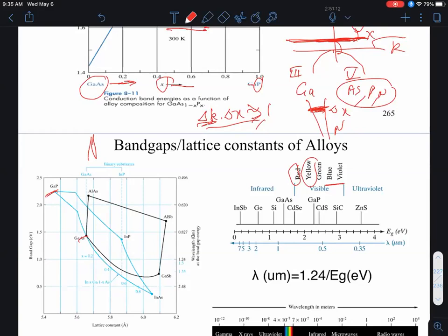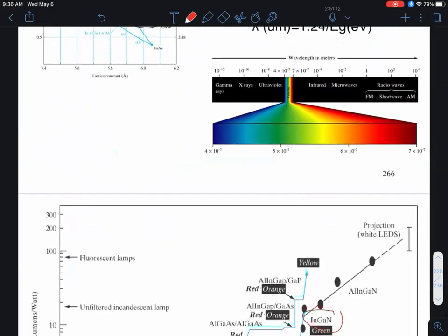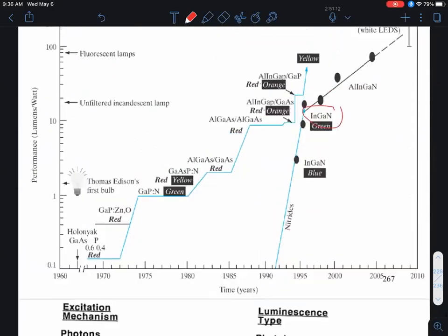Not only that, for some very interesting reasons, even though these nitride semiconductors are actually not very defect free, they have a lot of dislocation type defects in them, for some reason Mother Nature was kind to us. She decided that these defects wouldn't impede the optical output efficiency. Normally, if you have defects, it's the kiss of death for light output, because the defects can cause energy states in the band gap and give rise to non-radiative recombination. But luckily this one turned out to be a forgiving system.